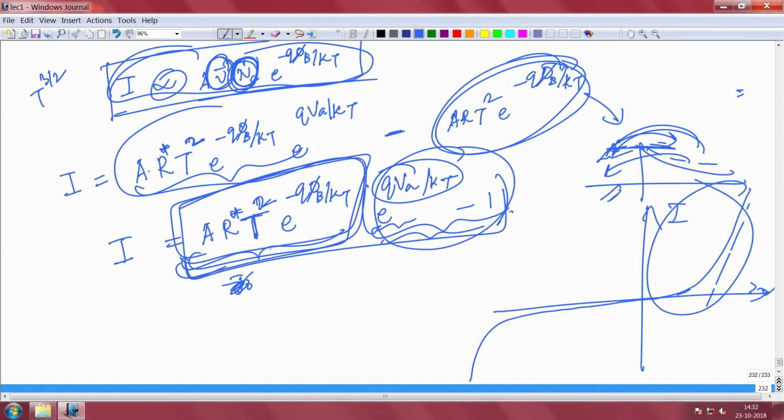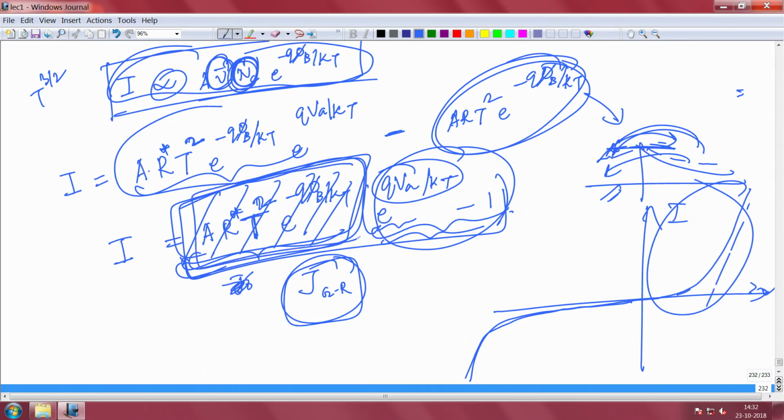Of course, there will be generation-recombination current. If you remember the generation-recombination current we did for the PN junction, it will also apply here. So, it will slightly keep increasing here, because the generation-recombination current adds a small component, but otherwise this component is your reverse bias component only. So, in reverse bias the current should be constant, and this should be the value from which you can find out phi_b if you know the temperature, but in reality it slightly increases.